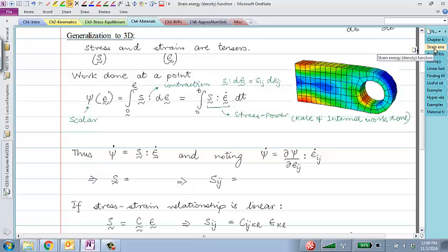I think this kind of expression for strain energy is suitable for small deformation situations. No, not necessarily. This is not only for small deformation. The reason for using this small deformation or the linearized strain tensor is because we are using Cauchy stress here. Cauchy stress is work conjugate, if you understand that term, to the linearized strain. If you go to the second Piola-Kirchhoff stress tensor, that is work conjugate to your Green-Lagrange strain. So exactly the same relationship would still hold for large deformation cases also.